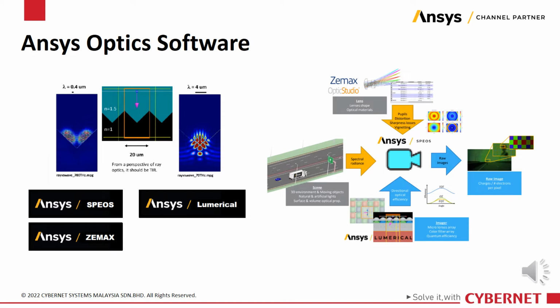The size of the lens group is about several millimeters. Each pixel of the CMOS is several microns, and the pixel size of the display is several tens of microns. Zemax is recommended to optimize the lens set. The crosstalk phenomena of CMOS and the luminous behavior of the display are suggested to be analyzed by Lumerical.